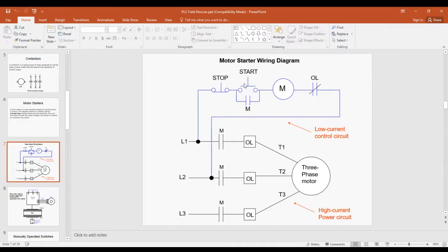Your fill-in circuit or latch, and then your reset or your stop button. So that you're already familiar with. So there are 3 levels of relays you want to know about. First is the basic relay. From that, we have a contactor, which is just a heavy-duty relay, usually 3-phase. And if I add a protection circuit to it, then we have a motor starter.